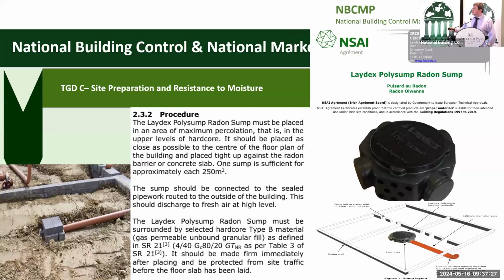The radon sump. So you can see here, consider that couple of blocks stacked on top of each other. Would you consider that suitable? Materials fit for purpose? No. The DOP for a block doesn't say it can be used for that. And this is really where people need to go back and actually check.